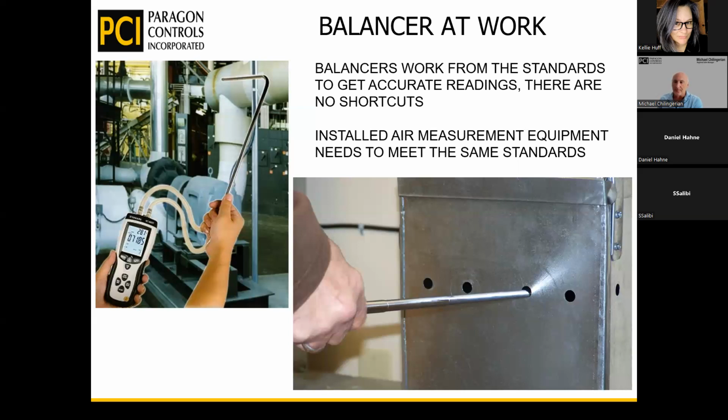or an outside airflow measurement. There is a little bit of a problem from what I've seen, in that because there are these dynamics going on within ductwork or an outside air, when the balancer does his job, it's very rare where he'll go and take airflow measurements at 100% and 75% and 50% and 25% and something low like 5%. So when he takes an airflow measurement, he's taking it at full flow. And we don't really know how the dynamics of the airflow within the duct really change, because he's only taking it at one reading. So this is something that's kind of a gray area after the fact.